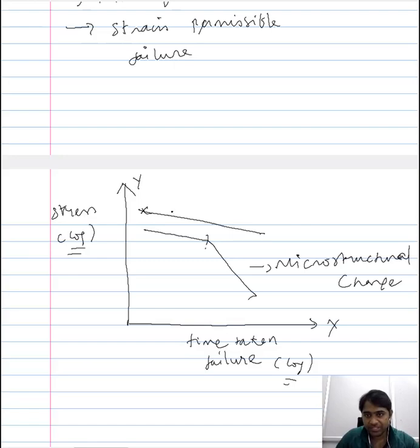So each of these data points here represents one stress rupture test. And this is possible because we have sufficiently increased the stress that we involve in the creep testing, and that means the material fails quite quickly, and the time duration for the overall stress rupture test is small, or rather half of the minimal time taken for the creep test. This allows for numerous stress rupture tests, giving you sufficient data points to plot the relation between stress and the time taken for the failure.